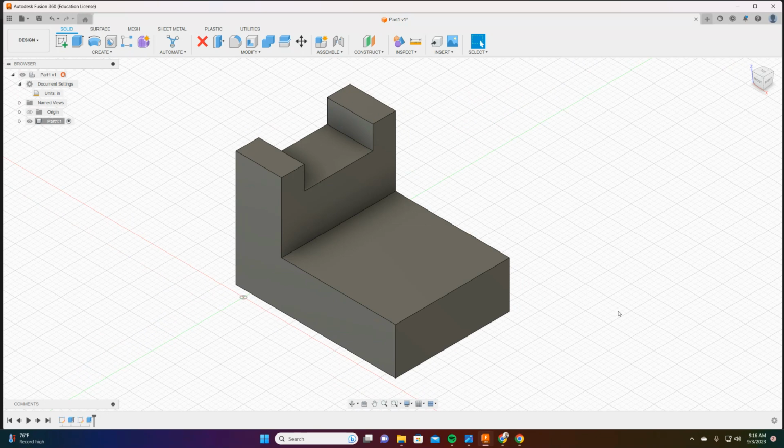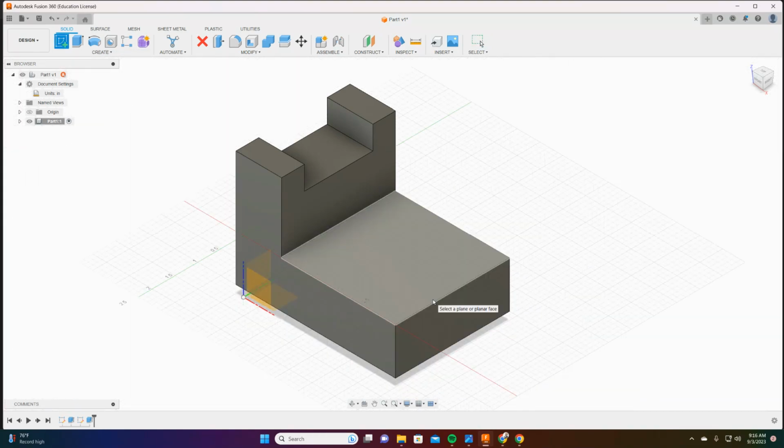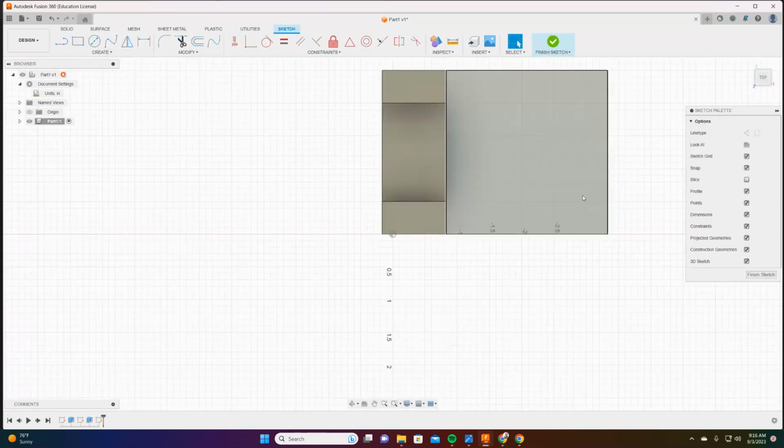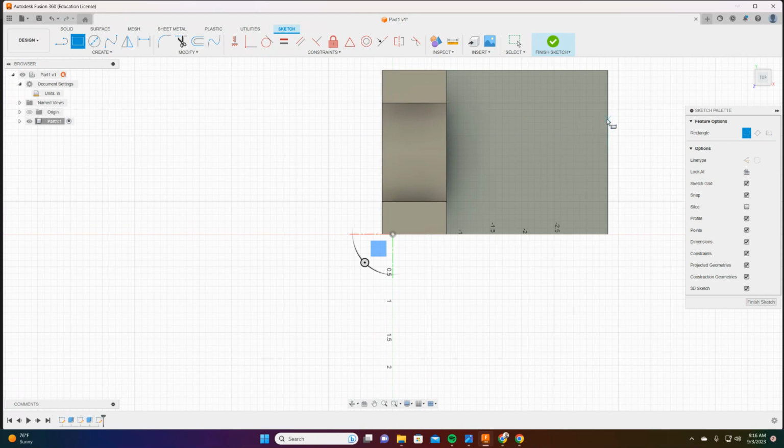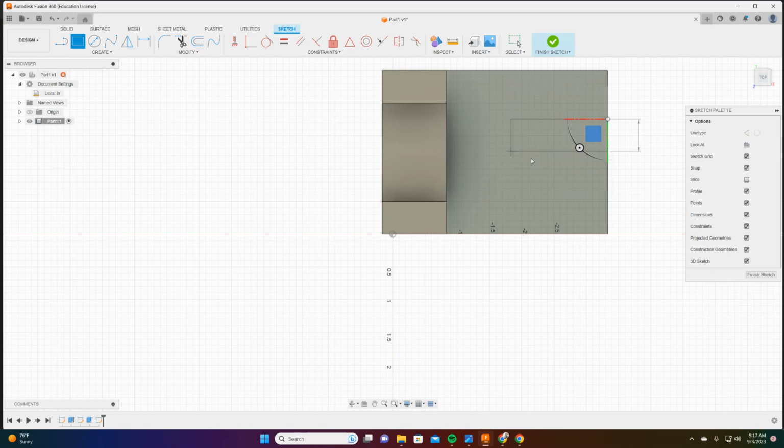And then the last piece for shape 1, we're going to create a new sketch. I'm going to come onto this, I'm going to do it right here on the top. So we're doing our orthographic, so it always jumps us right into that top-down view. I'm going to add my rectangle again, make sure I'm on this edge line because I want to bring it in. I'm going to dimension this last one out, which is going to be 1.5 wide, 1.5, and then my width on this is going to be 0.5. And I'm going to hit the Enter key to select it.